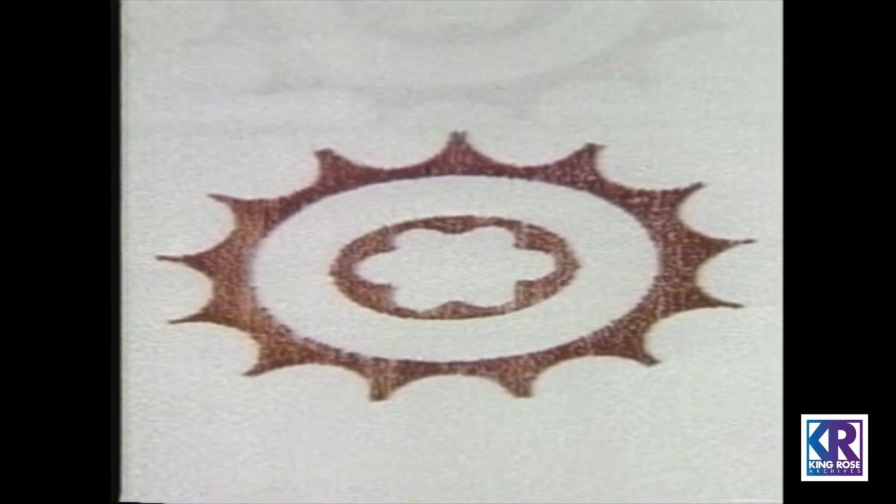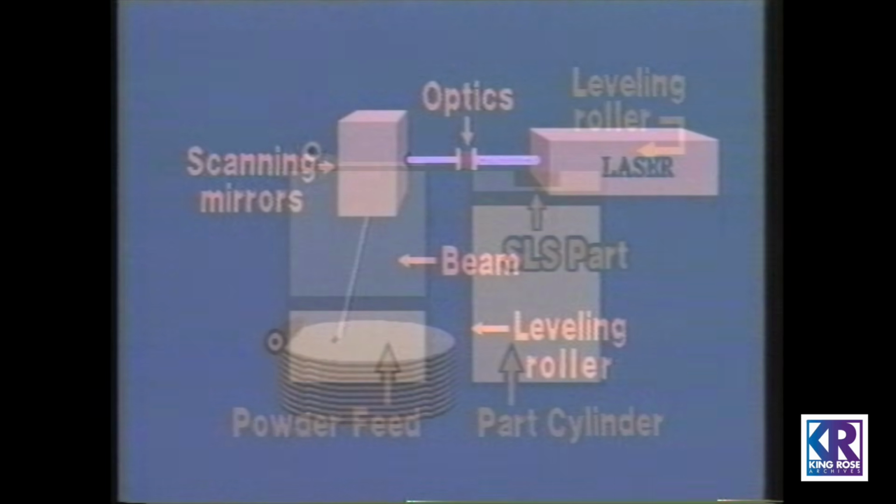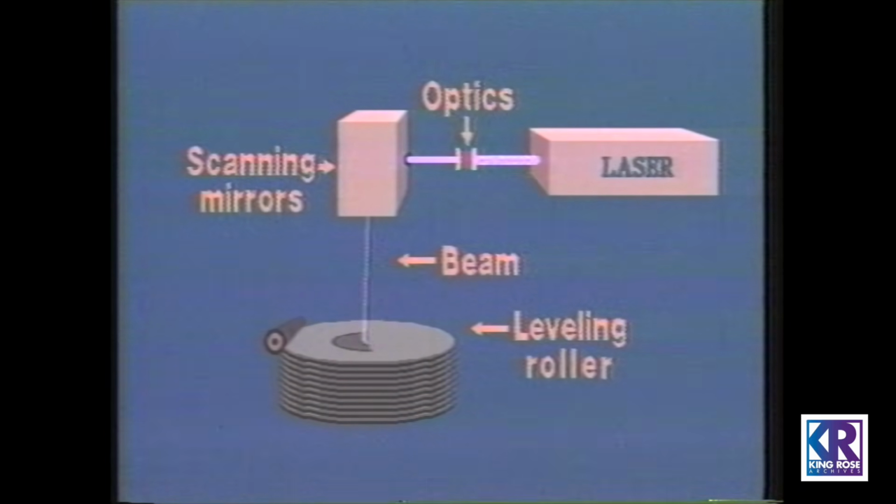A layer of powdered investment casting wax is spread by a set of rollers to a precise thickness. A laser beam is then rastered across the powder to sinter it into the desired shape. Once this step is complete, another layer of wax powder is deposited and the process continues with the next slice in the design. Each layer is supported by the preceding layer during production and then carefully laser sintered to ensure good bonding and sufficient densification of the wax powder.